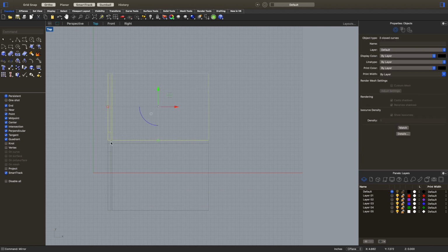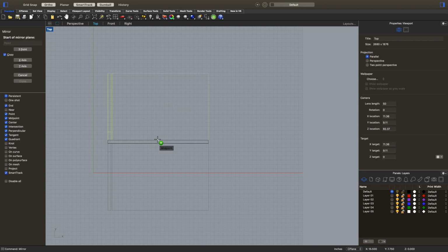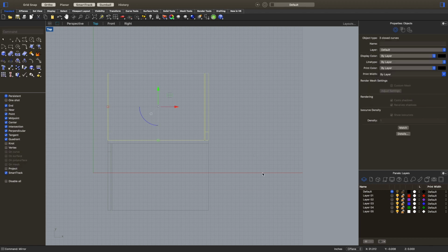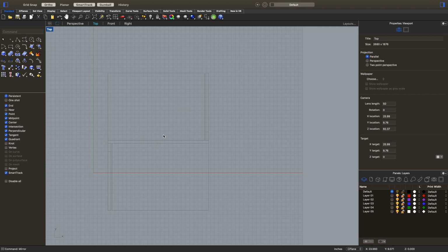You don't want to do it on the midpoint on this rectangle because that's not in the middle. It's pushed over. So use the midpoint on this object. Draw straight up, and where it says copy, uncheck that. That will be on the command line if you've got a PC, and then click. By unchecking that, it deleted the original one. Otherwise, you would have to do it afterwards.